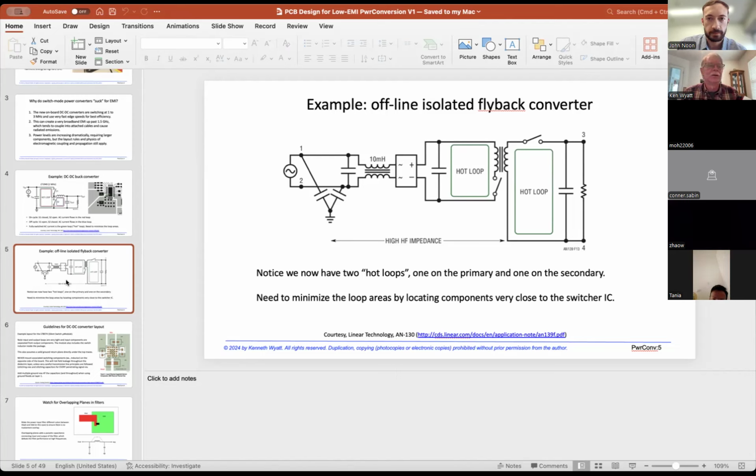Now there are software packages that are rule based. The rule checkers that companies like IBM originally came out with, and other companies, are nice for when you're laying out the circuit board, but for just predicting the EMC performance of a product using a simulator, you're probably not going to be successful.